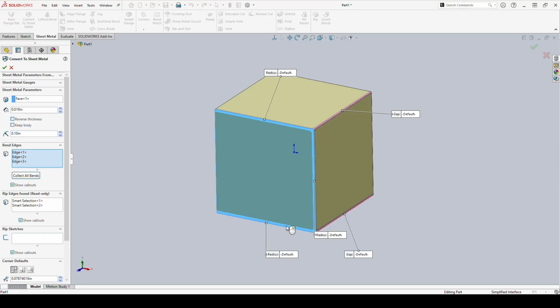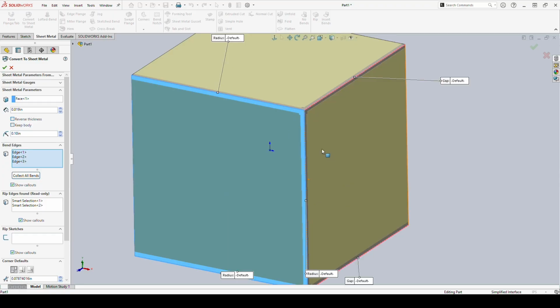But now I'm going to talk about this extra piece here. And this extra piece is creating these bend edges. So what these bend edges are is I am defining that if this is my base piece, that is what I selected up here, which is about to be important. I know I said I'd get back to it, and we're still going to get back to it. Everything else that exists, I can have bend from that. So I am saying that this is my bend edge.